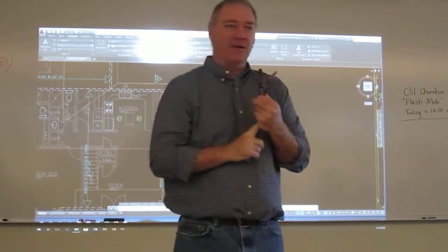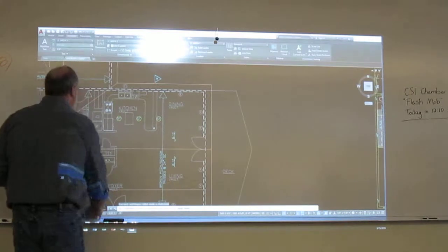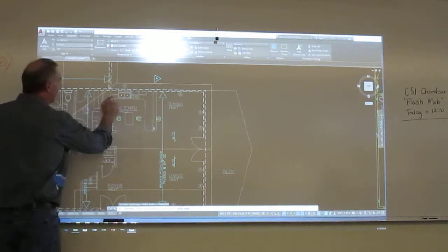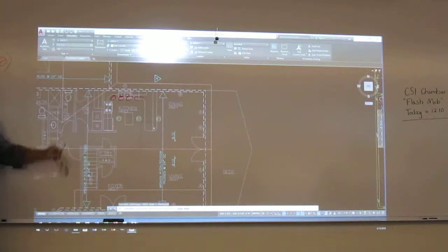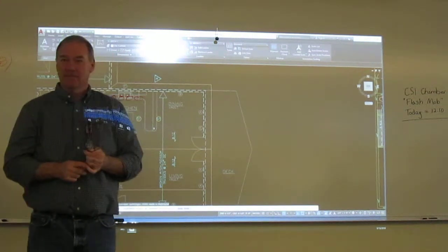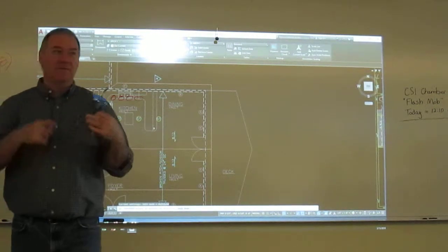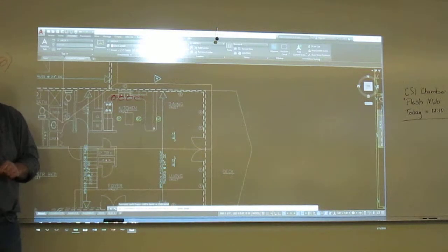Any major penetration. Now, there's a whole bunch of penetrations that's going to go into this thing, and they're going to go right over here somewhere. You're going to have a bunch of little things sticking up over here. What are these going to be? Vents for the plumbing. Your furnace is going to need a vent. Any combustible device, your hood above your range has to have a vent that comes out.